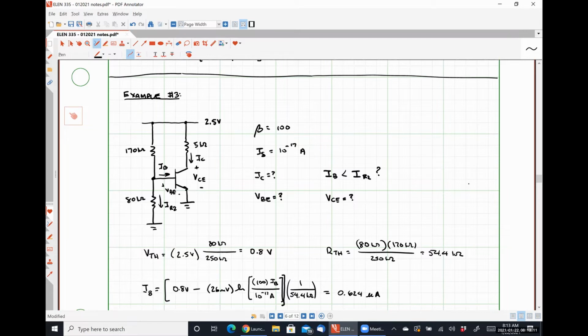Where that's going to come into an issue is if we look at our diagram here. What if that 80 kiloohm resistor changed by 1%? So it will get increased in value by 1%. What would happen to the base emitter voltage? And let's say that we can neglect the effects of the base current there, right? So a 1% increase in that resistor R2 would cause roughly a 1% increase in our base emitter voltage VBE.